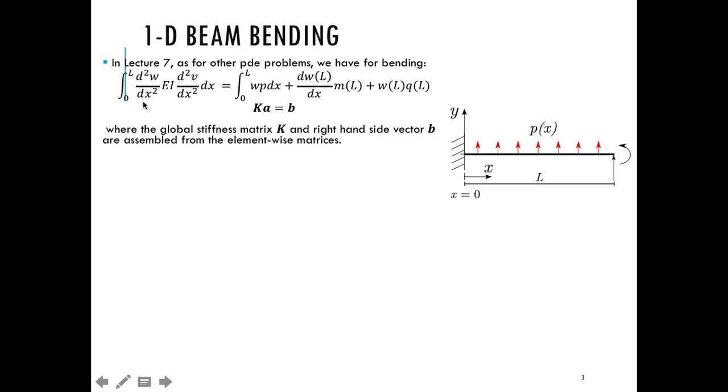So basically this weak form, once it's been manipulated using the Galerkin approximation, can also be written as our standard finite element problem given by this expression right here, Ka = B, where this is our very familiar K being our global stiffness matrix. A is our nodal vector with the degrees of freedom, and then B finally is the global right hand side vector.